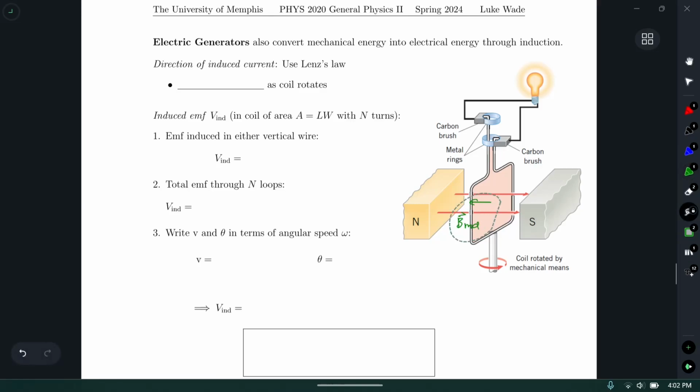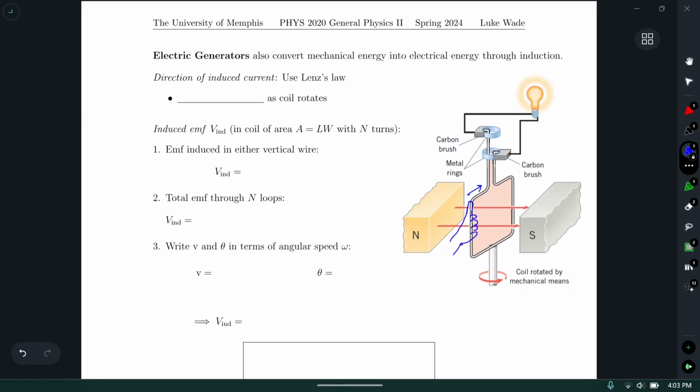And the only way we can have that kind of induced magnetic field is if we think about the second right-hand rule. If our field is to point to the left, our fingers should dip into it that way. And that would mean our thumb is holding on like that. In other words, current flows this way around the loop. As the loop continues turning, eventually it will see a decrease in the flux through it, and that will make current flow the other way. And that is why the direction of current flow alternates from a generator; that is alternating current.